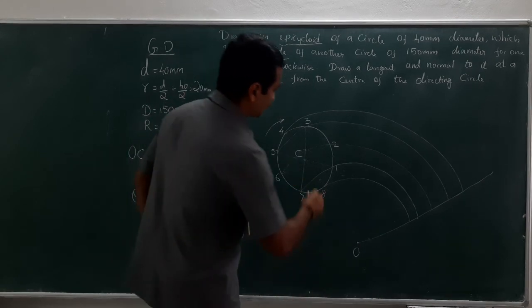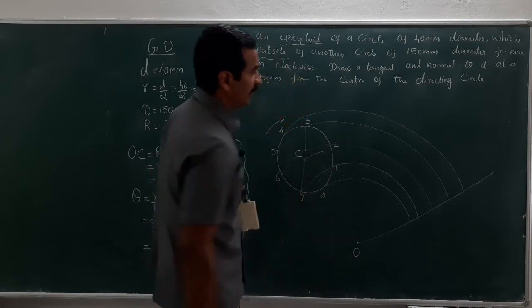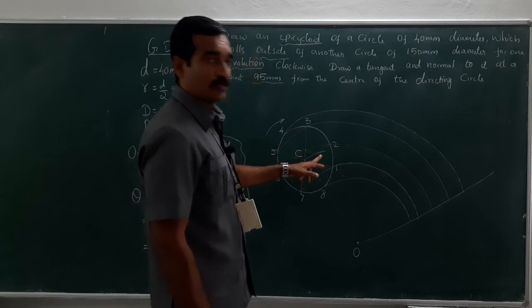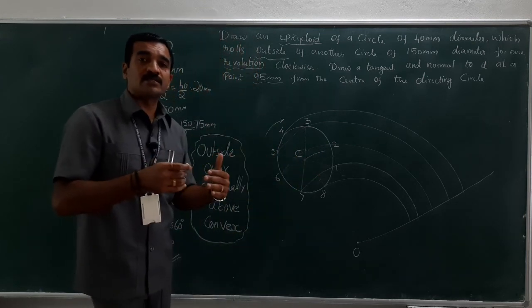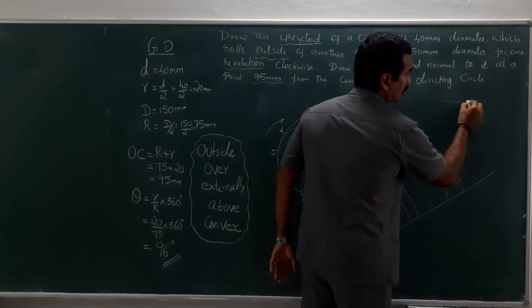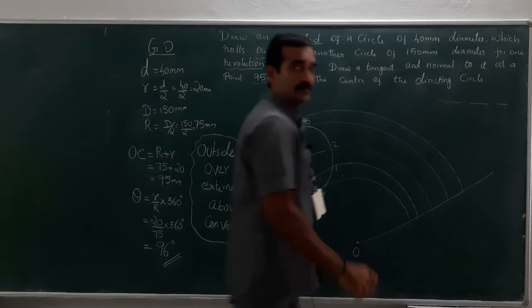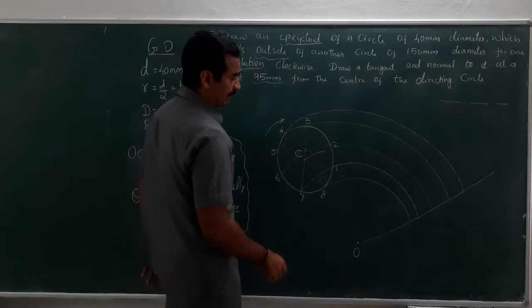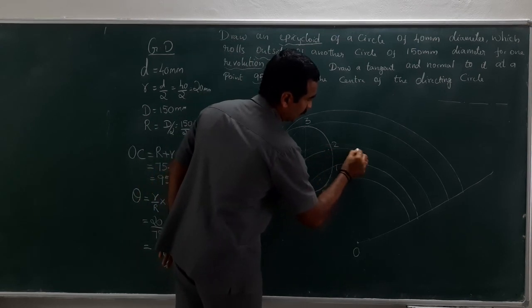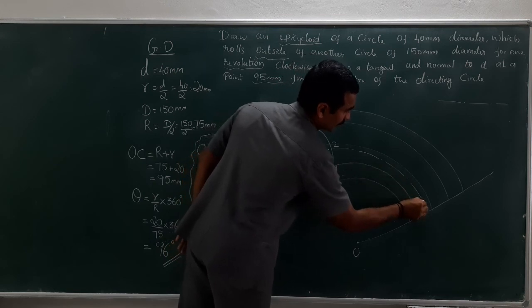The center notation, or the axis or the center, should always be mentioned with long line, short line, long line, dot or whatever, long line dot long line, isn't it? So similarly in that same manner I am going to mention here long line dot, long line dot, long line dot.